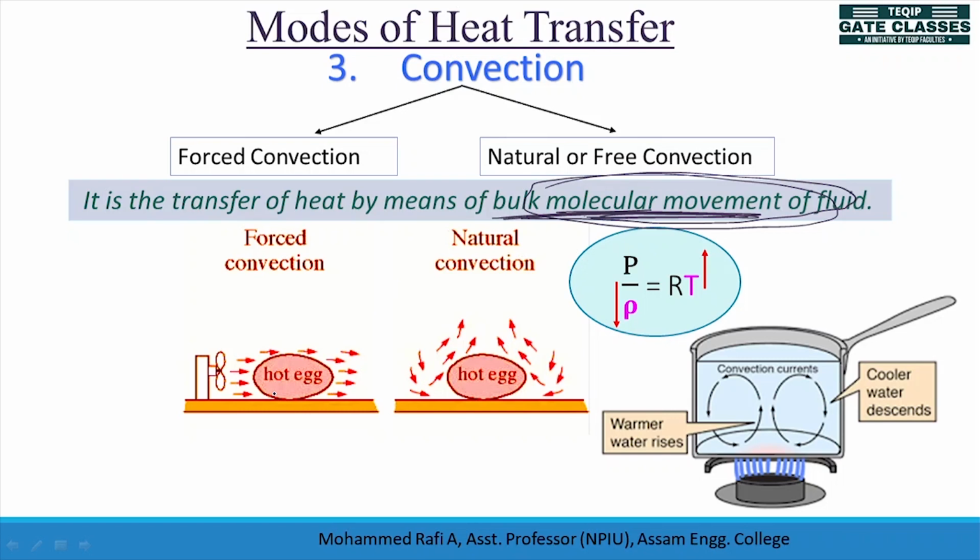But if you are in a hurry, either you will use some external force, either you will use some fluid, either you can use a fan or something to enhance the heat transfer. If you are using any external fan or something like that, then it is called forced convection. If you are doing heat transfer with the natural method without any external help, then it is called natural convection. So there is a major difference in convection, forced convection and natural convection.